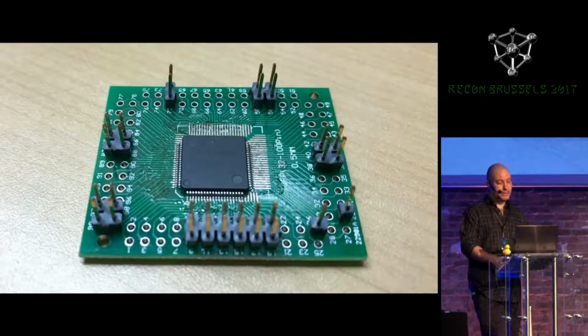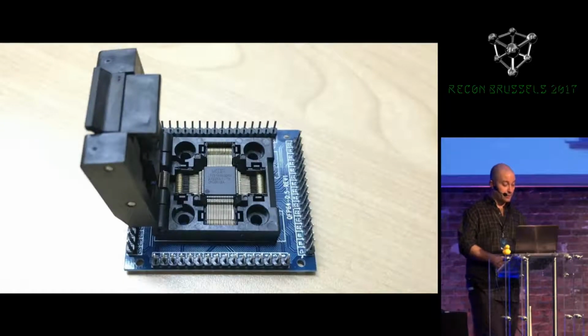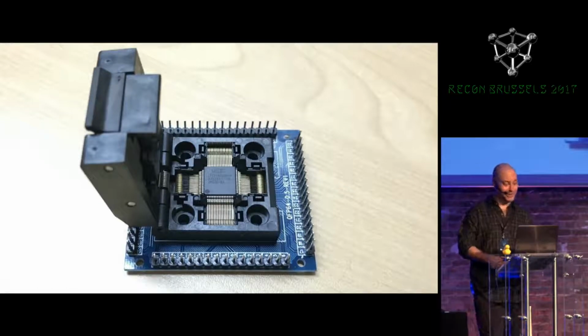This is the LPC 1751. And you can see I've only populated some pins on the breakout board. This is because really I only need to power the chip to enter the bootloader mode and to have the serial access. I'm not interested in so many of the other peripherals, so I try to keep it simple. This is an LPC 2101, another member of the family. And this is an LPC 2148 on a nicer breakout board that I found with a ZIF socket. That's a lot more convenient to work with if you're going to be changing between a lot of different chips.